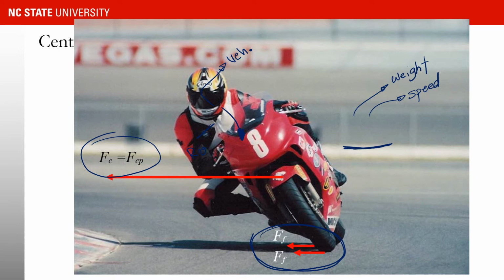Think about the elevation or super elevation of the road. So if you are driving on the road and the road has a slope like this, you can imagine this like what you see in NASCAR races. You see that the track is really sloped and it has a high super elevation. So this force is going to maintain you or push you toward the center of the curve, and if you have this, you can go through the curve much faster. So here the curve is like this.